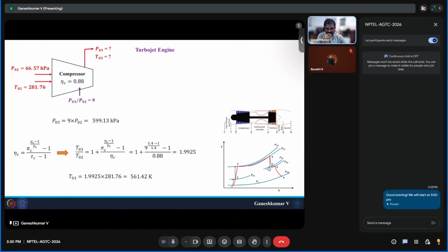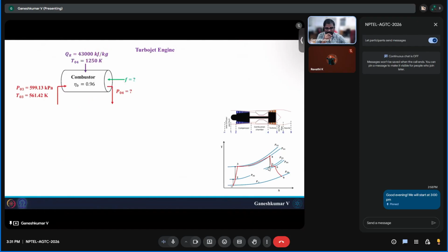And you will also see, here we are talking about just the stagnation temperature. This is not a static temperature that you will feel there. This is a stagnation temperature. Okay. So now this is the stagnation temperature at the end of the compressor. Now, since we found all the terminal temperatures at the end of the compressor, we will proceed forward with the combustor.